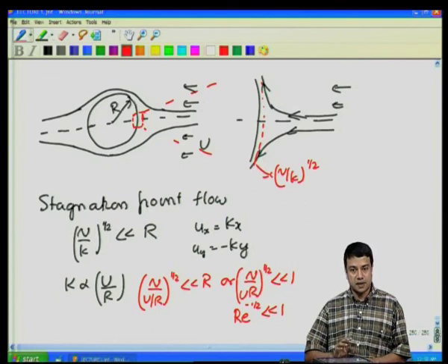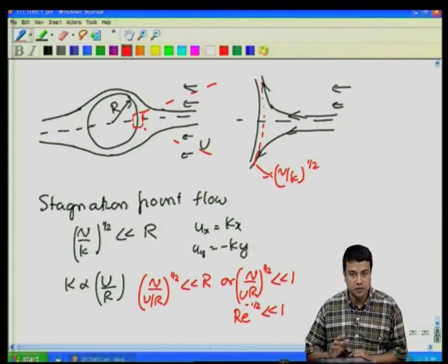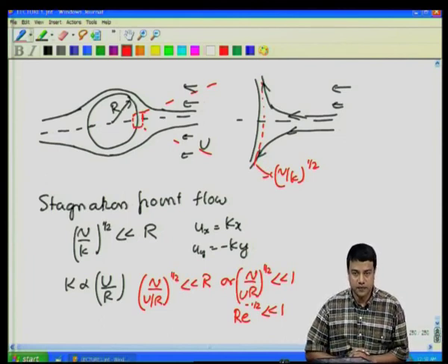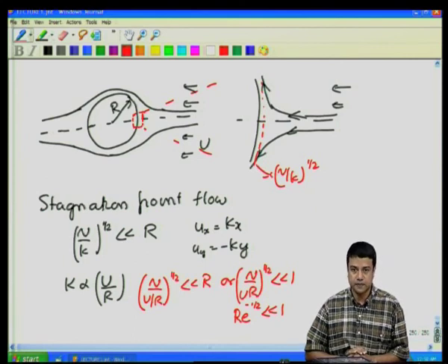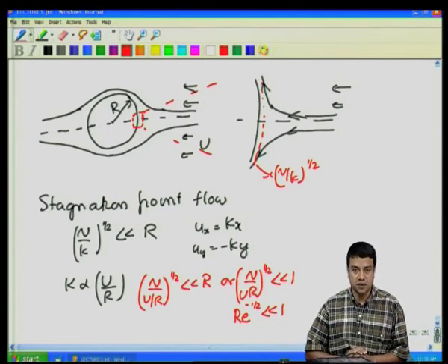We will see that in the next lecture, but let me just say that not all velocity profiles can be reduced to boundary layer solutions. When we looked at heat and mass transfer, we found that any velocity profile does have a boundary layer type solution for the concentration or the temperature field. That we had got as an exact result in heat and mass transfer.